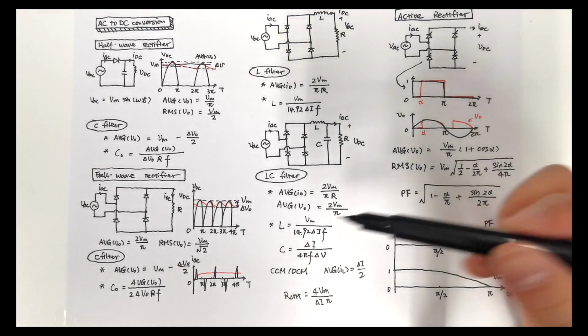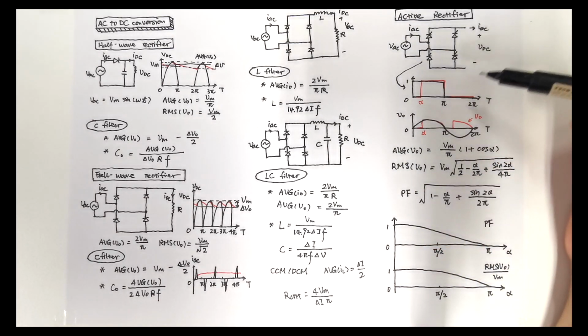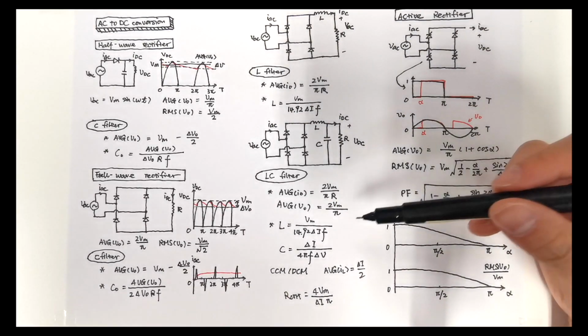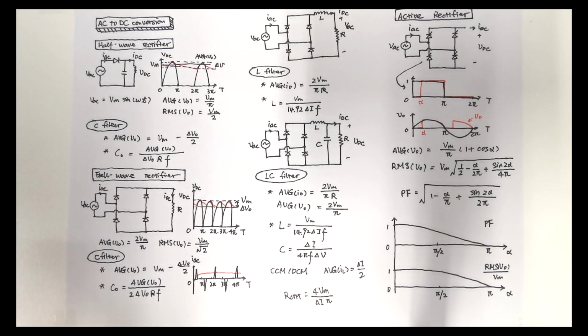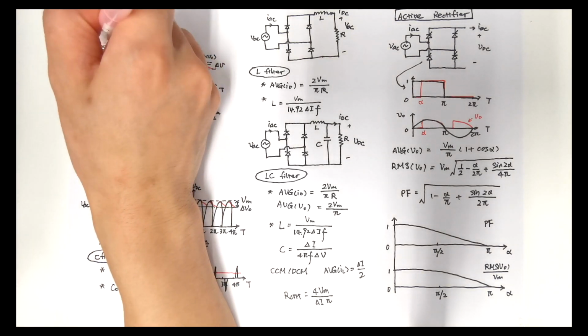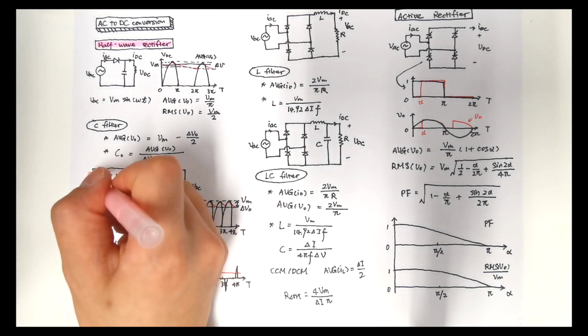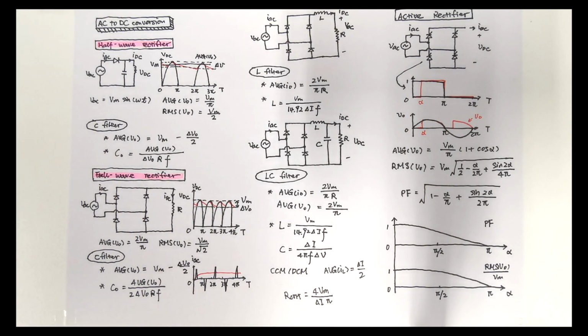In the same way as the 4-diode rectifier, we can design the LCL filter for our active rectifier. The design process is the same as for the 4-diode rectifier. In this video, we learned 3 types of rectifier: the easiest way using the half-wave rectifier, and then we learned the full-wave rectifier. And by adding control to the rectifier, we also learned the active rectifier.